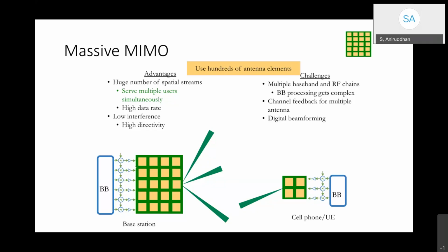If you need to have phase shifters and amplitude VGAs and so on in the RF path to include hybrid beamforming, that would increase the power consumption, the area, and the size of the base station. So with that in mind, they have opted to do only digital beamforming.